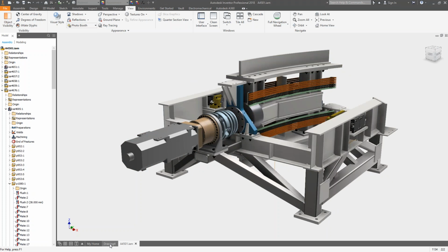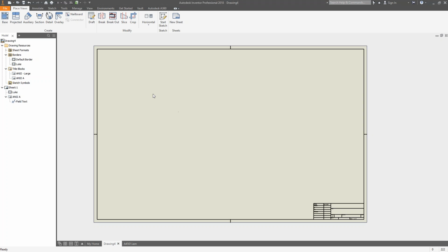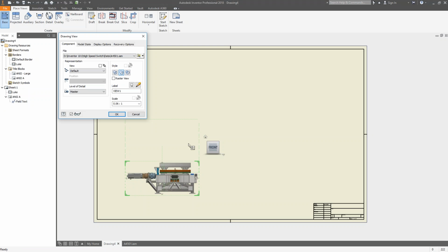when we create our drawing view now, so when we do our base view, a couple different ways to do it. Again, I tend to do things either off a right click or a keystroke. So base view is where everything starts. This allows you to create those default base views. So I'm just going to right click base view. It knows that I have an assembly file open, so it searches out and looks for that particular assembly file, and it automatically starts to place that view.